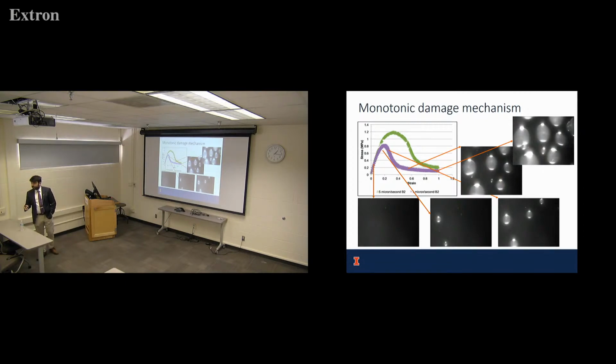So in those polymeric materials, they do a lot with the growth rate and why they grow. And basically what you see is those cavities that form later, they actually grow faster, but that's only until they run into another cavity. So that's the big issue we saw there. It's like this one, for example, this small one, it grew quite a bit from here compared to its counterparts, but then it started running into this one and stopped growing. So we did characterize things like that, and it's in the paper, just didn't present it here. Yeah.